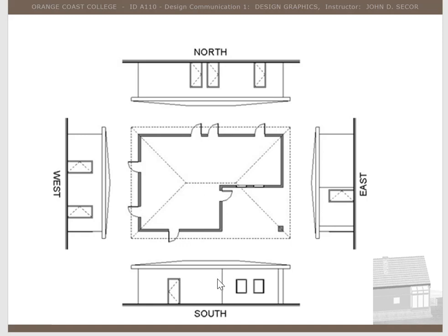Here, once again, you would have a line here and it would L-shape into these little teeny back windows, and there they are. Here is a door swing, and there is your door right there. That little teeny triangle, that point there, shows where the hinge meets on the door. Over here, as you orthographically project these lines, are the two doors represented right here. And even though this is upside down, you would project these lines and you've got 1, 2, 3 doors on this side.